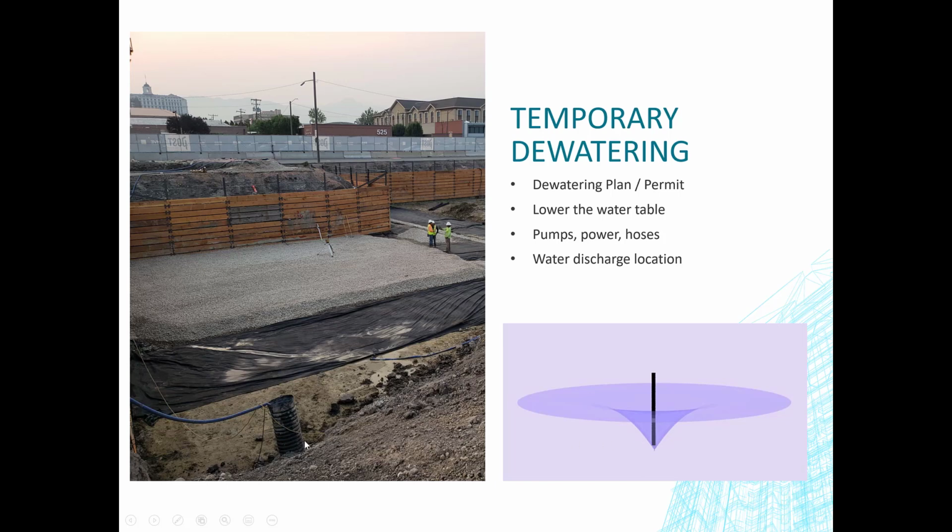But think of this temporary dewatering point as kind of like a well. Dig a hole, put a bunch of gravel there, water starts coming into that gravel, and you start pumping it out. Well, what it does to the water table is it starts to do this.